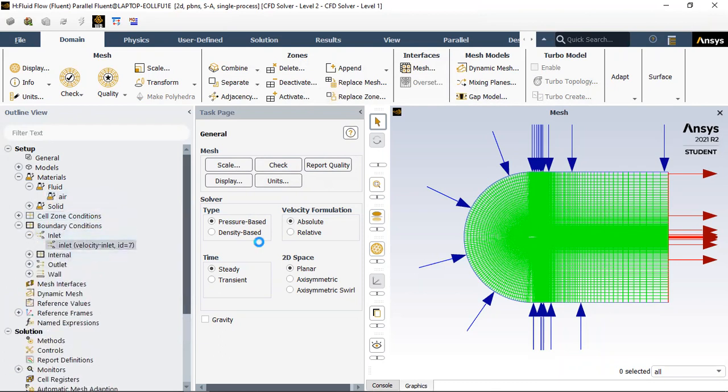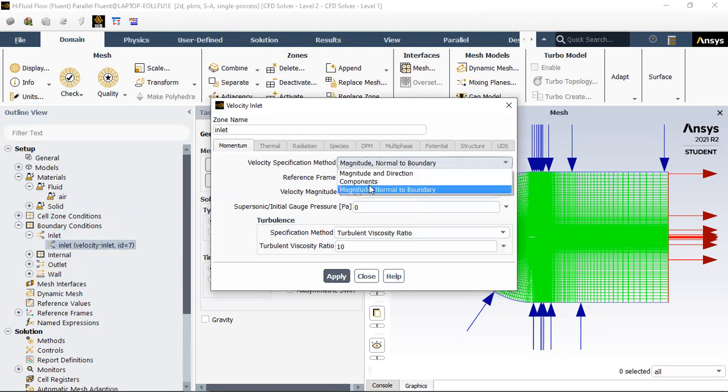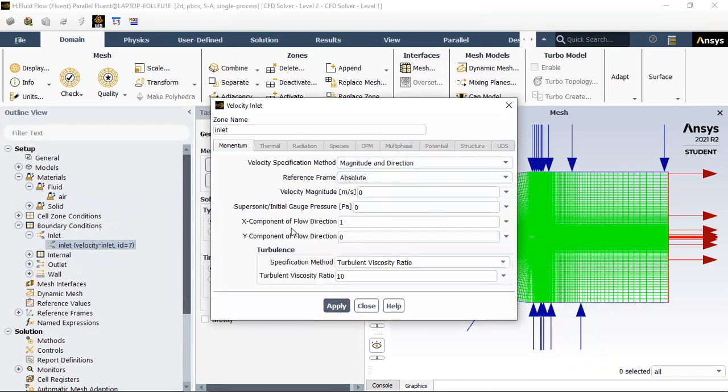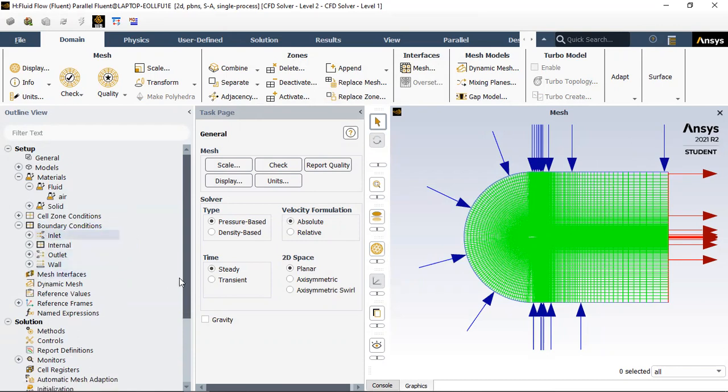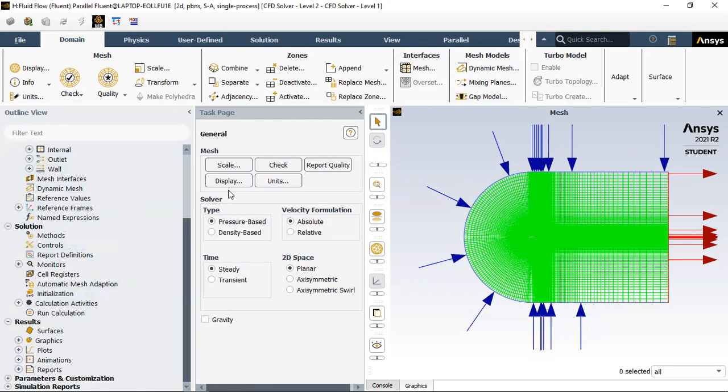Okay. So the inlet here we defined how the flow is going to go through the inlet. This time we're just going to put magnitude and direction. I chose, I believe, 3000 Reynolds number, which is 43.9 meters per second. We can see that the flow direction is just the x direction. So these arrows are not quite okay, like the fluid is just going to go towards the right. This doesn't actually show the airflow. Okay, so that's what we're going to change this time for the simulation.